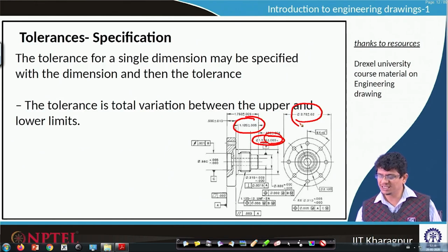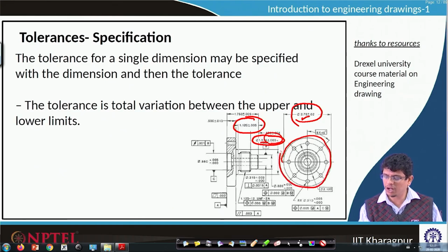When machining is done and the product comes out through this engineering drawing sheet and goes to quality check, mainly the quality control people check whether these tolerances are met for that object. If someone measures the diameter of that outer circle and it is 2.75, perfectly fine.